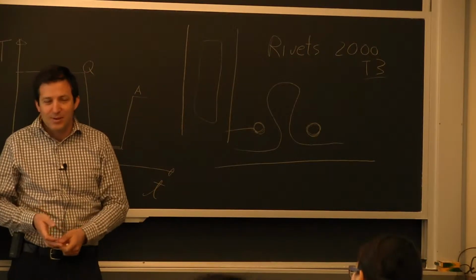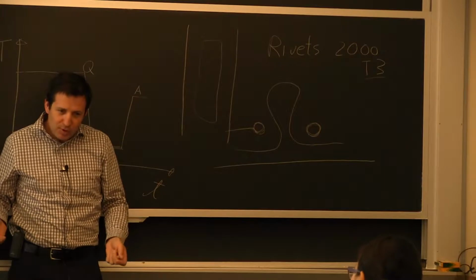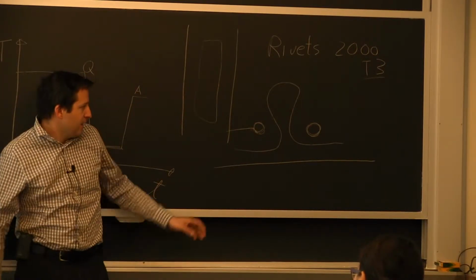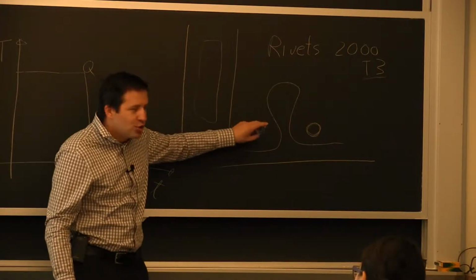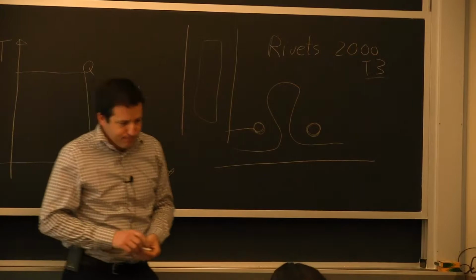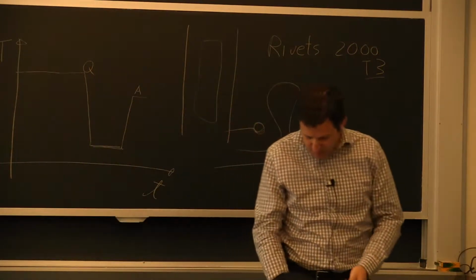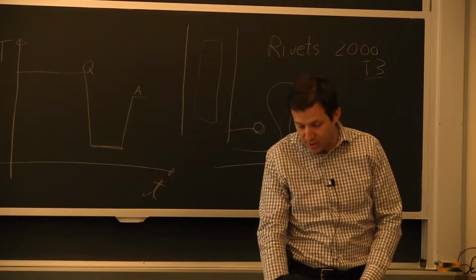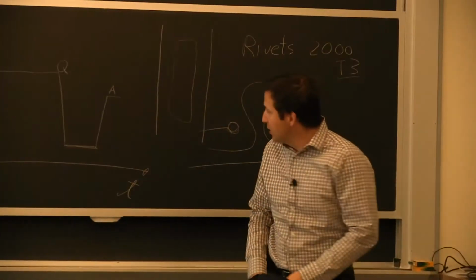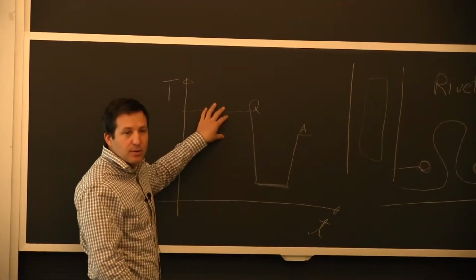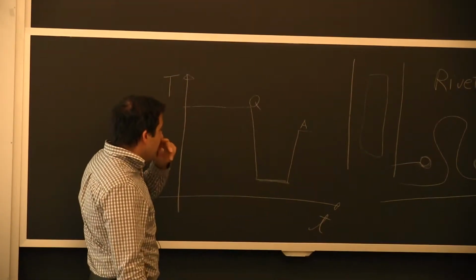So too small, too big, they don't do a whole lot. It's in between, and that's why you go through a peak here. And the exact shape of the precipitate will vary over time. The relevance of it with respect to this class this semester, as Professor Eager mentioned about welding. So in welding, you'll heat up the material in the heat affected zone.